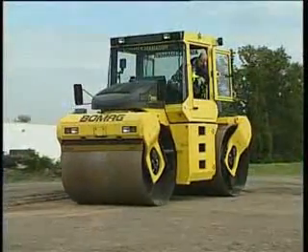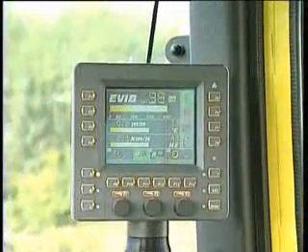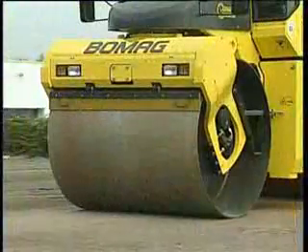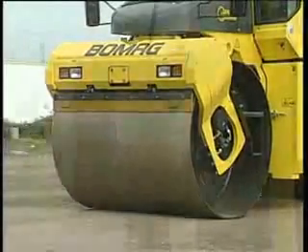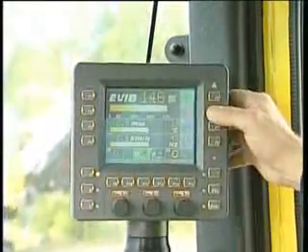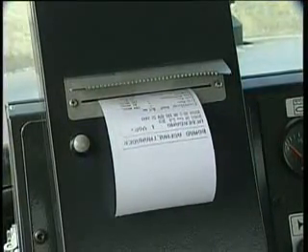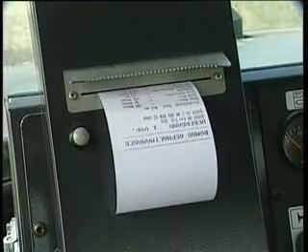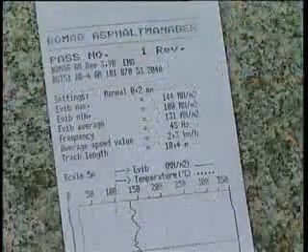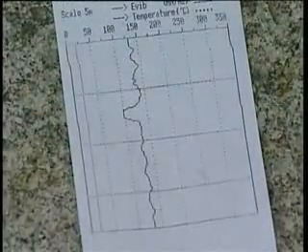Rollers with the Asphalt Manager can also be used as test rollers for the road subbase. The aim of compaction is to achieve a uniformly high load-bearing capacity. For this, a surface record is made of measured EVIB data from an established rolling pattern which can be printed out directly on the job site. This means that soft spots can be identified quickly and precisely corrected. A printer is available as a system accessory.